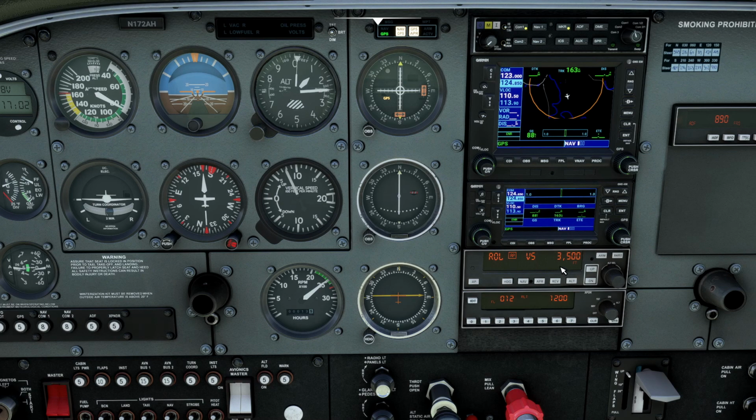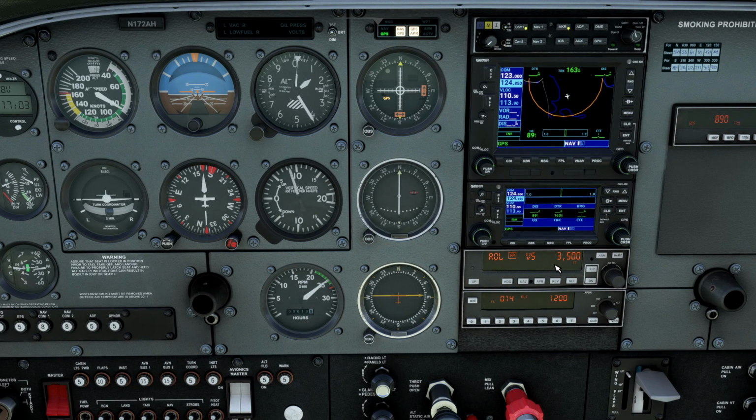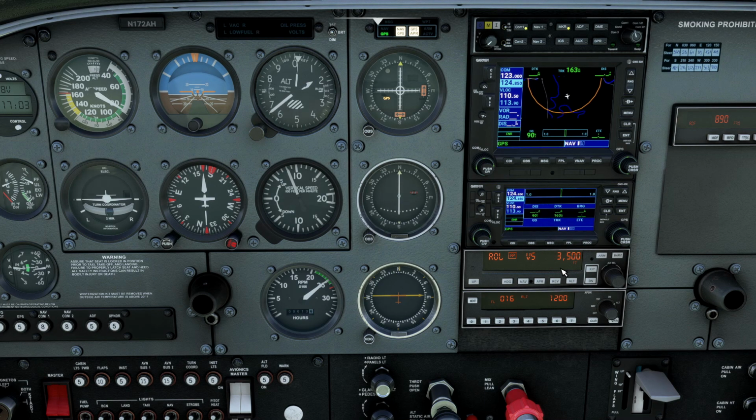Because of this little quirk in the Flight Simulator autopilot, there's not a limitation in the manual for the autopilot of a minimum engagement height, but good standard practice for most autopilots is to be at least 500 feet off the ground before you engage the autopilot, and that's what I would recommend here. Higher is better. 1,000 feet is probably preferable, but if you're quick enough, you can get it on after 500 feet without getting too close to the terrain.